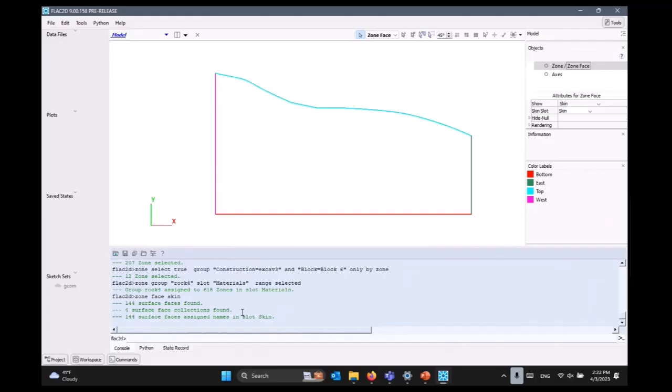But this is all with geometry. Next step would be material properties, excavations, and interface properties, and then just cycle it to equilibrium. So that's how you typically approach a bit more complex models, a bit more complex geometry, but the whole picture is kind of the same, I would say, or strategy. So let me just open an existing project. I'm not going to even save this one.